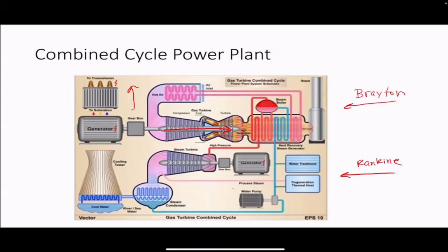So following the water pump in the Rankine cycle, remember, we pumped to the boiler. And here, that's being pumped in this heat exchanger that is getting heat from the Brayton cycle, or the exhaust from the Brayton cycle. And then it's coming out at higher temperature and pressure, going to the turbine in the Rankine cycle, which then comes out. And you even could use cogeneration here.